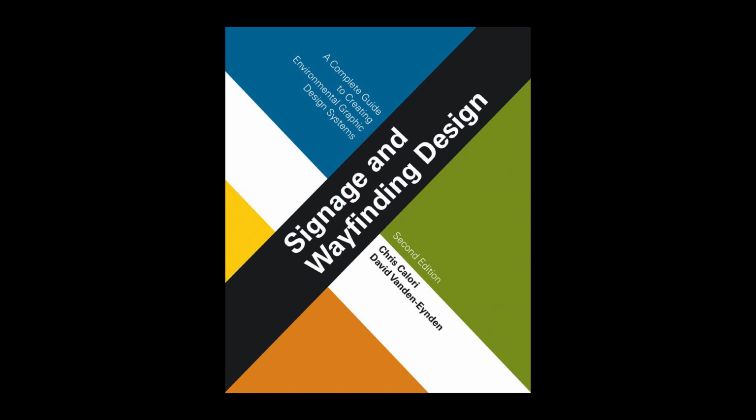Porcelain enamel coatings are generally used on flat sign panels, as these coatings don't readily conform to complex three-dimensional shapes. Few sign fabricators have porcelain enamel equipment, so most porcelain work is subcontracted to specialty suppliers. A porcelain enamel sign is shown in figure 5.68 of chapter 5.